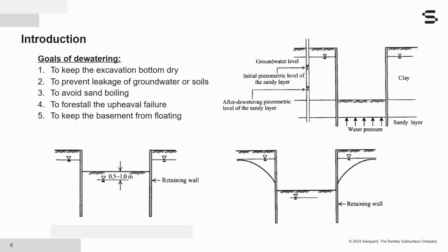Now, as is natural, with the completion of the excavation, we start constructing the basement of our structure. In sandy soils, with the light weight of structures during the stage of basement construction, where only the weight of the basement is considered, the phenomenon of floating of the basement is likely to happen if the weight of the structure is smaller than the water pressure acting on the foundation base.